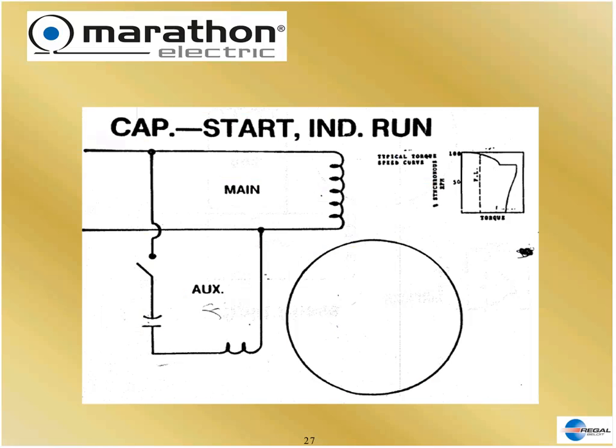Here's a speed torque curve. Notice the big amount of torque we have here to start the motor to accelerate. We still have the switch, which is over here, but we've added this device, which is a capacitor. So how did that capacitor get all this curve to move way over there and give us torque? Well, this coil, electric motors have coils. This coil has impedance that is frequency sensitive, and that impedance is inductive because it's a coil.